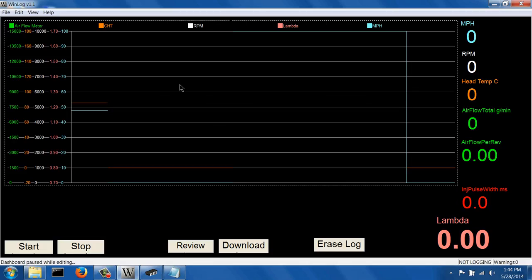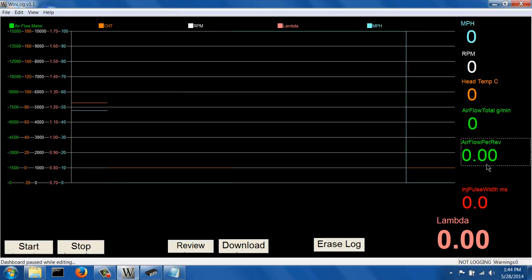I just wanted to point out that you can build these nice digital gauges that look like this, or analog, needle style gauges you saw in the other one, and you can put them anywhere you want on the screen, size them any size you want, make the numbers as big as you want, as small as you want, and highly configure the conversion factors from 0 to 5 volts to the units you want to see on the screen. That concludes this demonstration.